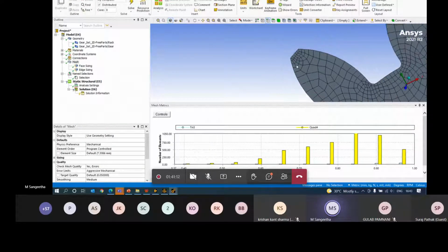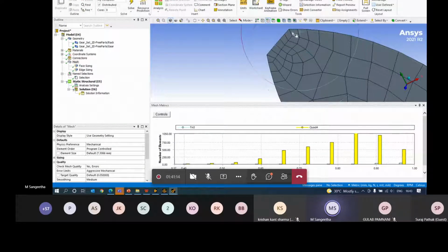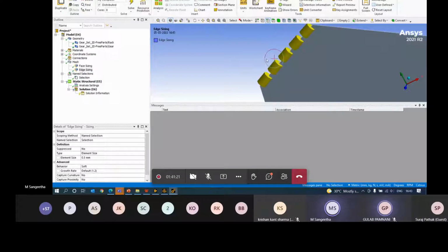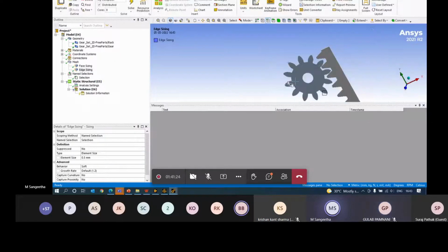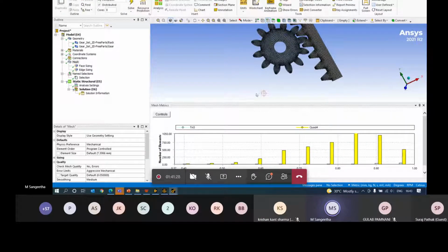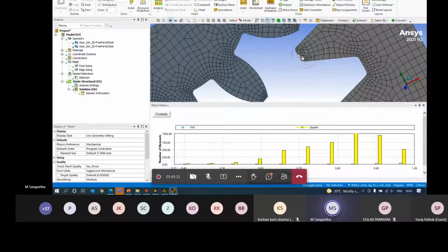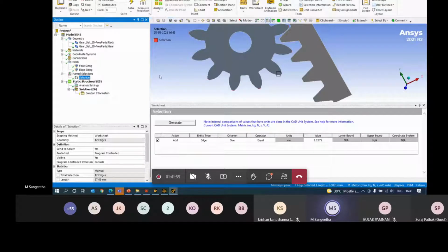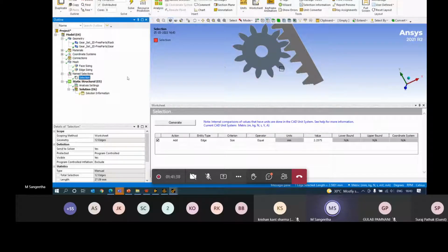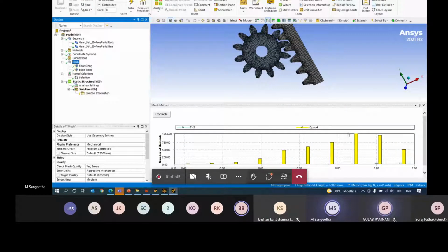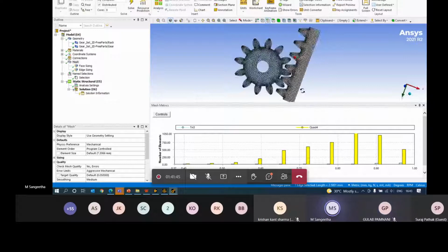Now when single elements were created, all this we have changed, and with 0.5 elements of size 5 getting assigned. So basically these are few techniques which we can use. And always here also it has created, so you can make use of name selection anytime for figuring out this kind of issues. And as of now, when you look at your geometry here, 0.7 to 1, if your maximum elements are coming up, that is quite acceptable.